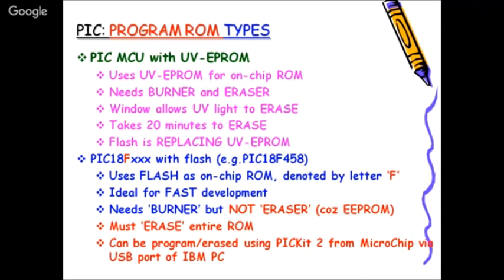So that controller, when your computer says delete only that much, allows you to actually erase that particular block or particular file. So don't treat a pen drive as just a flash memory. It is a flash memory with an interface to the controller. It is an embedded system in itself. So it's not only memory; there is a controller inside it, and that controller was customized to perform all these functionalities.